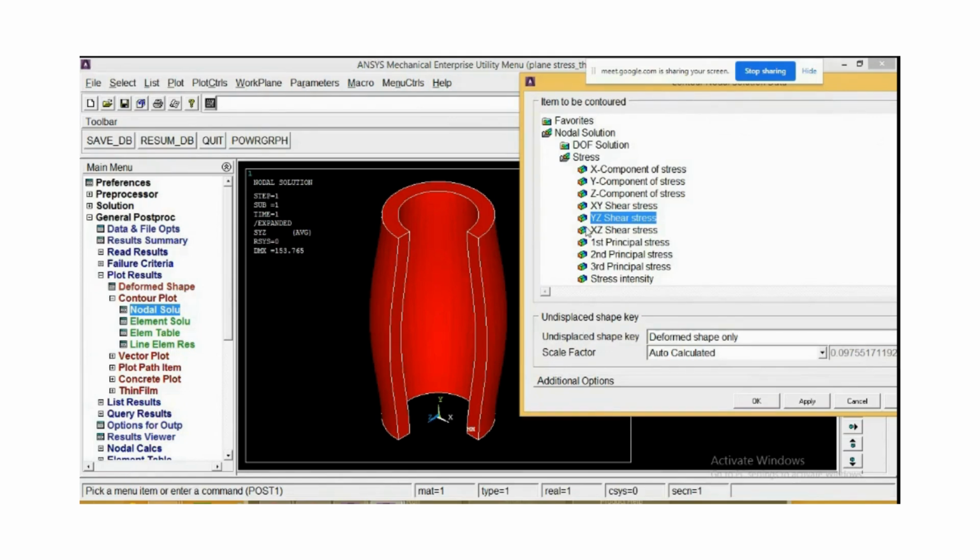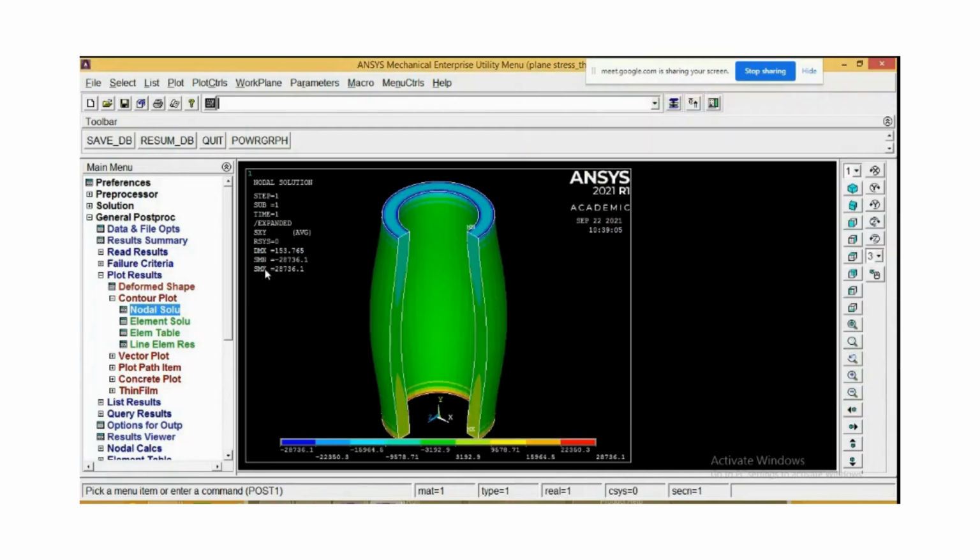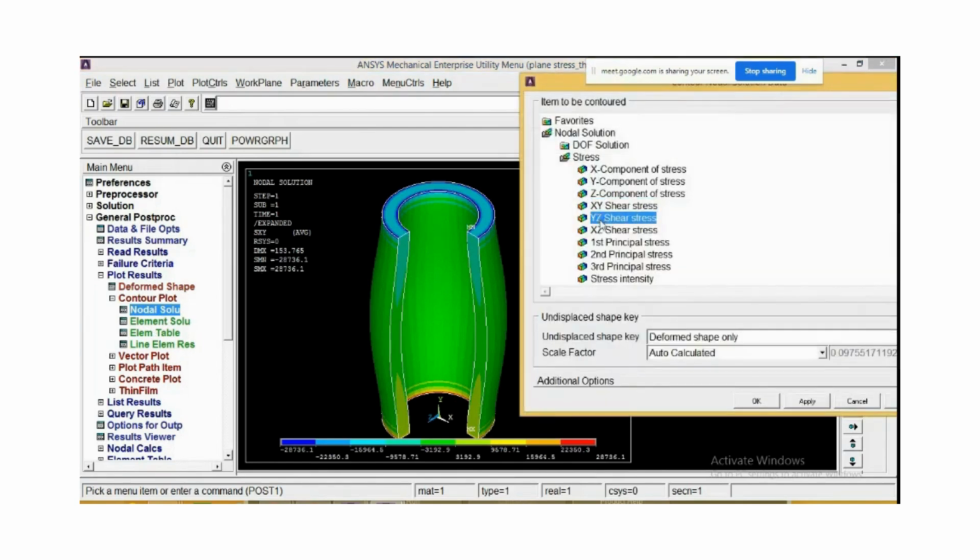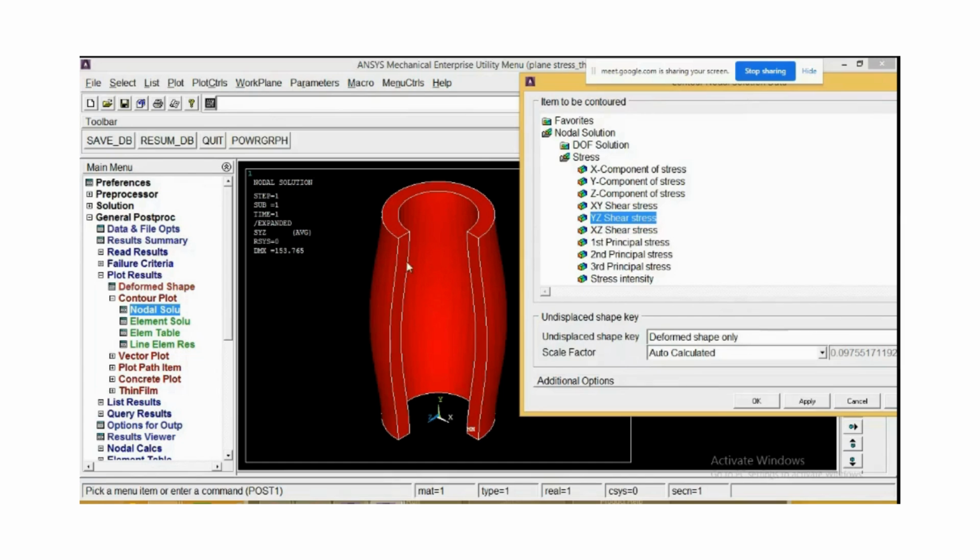Now shear stress you can observe, because this geometry is circular. Actually it will be showing zero, but the geometry whatever we have drawn, the z direction may be considering a different location and orientation. But you can observe the shear stress value, shear stress xy is present, tau xy is present. You can get some value here, but you observe the shear stress value along yz is showing 0, as well as along xz it is also showing the 0 value.